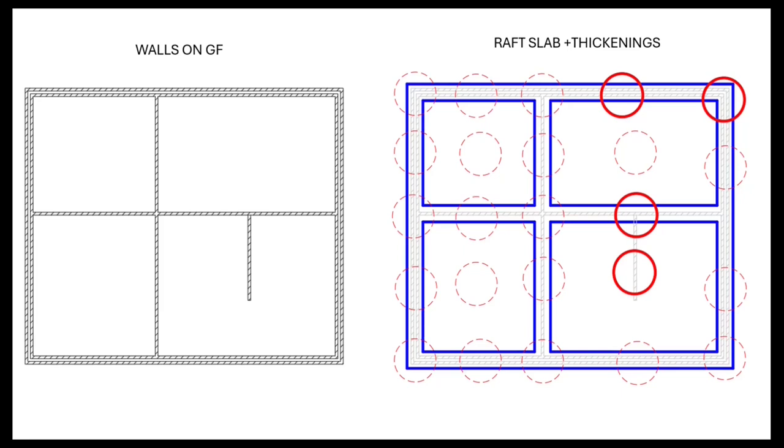So in this case, I would probably check only those 4 cases which are shown with solid thick red lines, and how to justify which parts need to be checked. Generally, we are looking at loadings. So if we have corners, we are checking the corner which has the heaviest loadings.